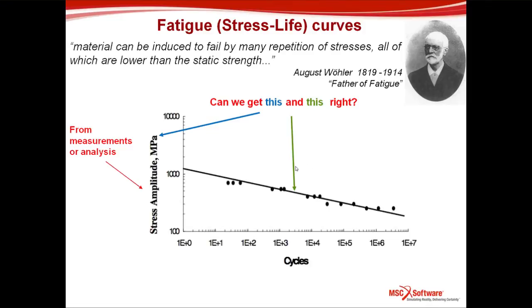So the key concept in fatigue is therefore to identify the material. This is pointed out by the green arrow, and the relationship between stress amplitudes and cycles that can be obtained at a given amplitude, but also to determine the loads. The blue arrow, this is what Adams provides, accuracy with regard to the loads. Of course, this could also be done experimentally, but at a much higher cost. So the fatigue code intervenes in taking those two models to predict the fatigue analysis.